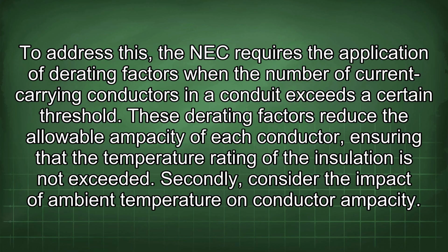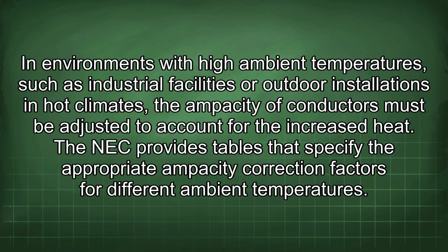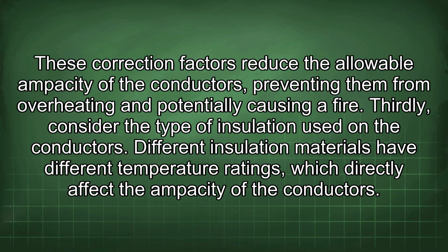Secondly, consider the impact of ambient temperature on conductor ampacity. In environments with high ambient temperatures, such as industrial facilities or outdoor installations in hot climates, the ampacity of conductors must be adjusted to account for the increased heat. The NEC provides tables that specify the appropriate ampacity correction factors for different ambient temperatures. These correction factors reduce the allowable ampacity of the conductors, preventing them from overheating and potentially causing a fire.